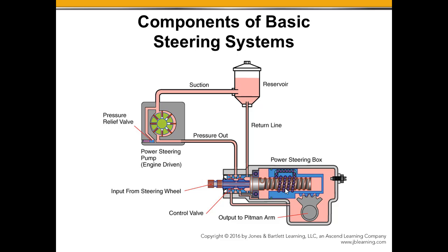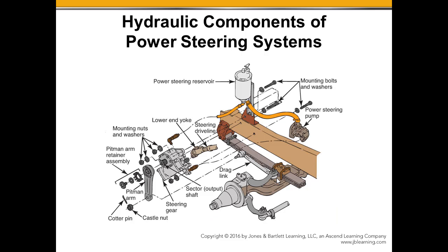These are all ball bearings here, and there are passages on the inside that allow those balls, as we are turning and rolling it, to cycle their way through that worm gear, up through the passage and back in. So they are recirculating those ball bearings back around within that worm gear.